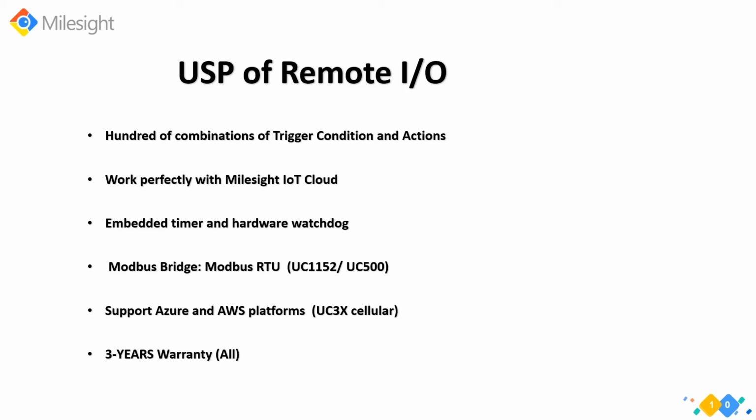And I want to emphasize the Modbus bridge. The Modbus bridge feature in the UC11 and the UC500 can convert serial-based devices into LoRaWAN-based devices and enables data transmission between the serial network and the TCP/IP network over the LoRaWAN protocol. Okay.